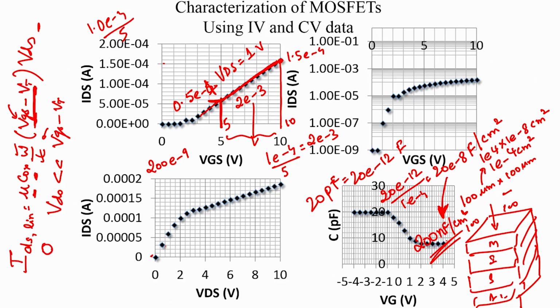Okay, so since we have made an assumption on the aspect ratio, let us say it is 10, and let us say the VDS is 1 volt, okay, and let us say we do not know mu, and therefore this slope must be equal to this number, okay. So which means that the mobility will be about 1000 centimeter square per volt second.